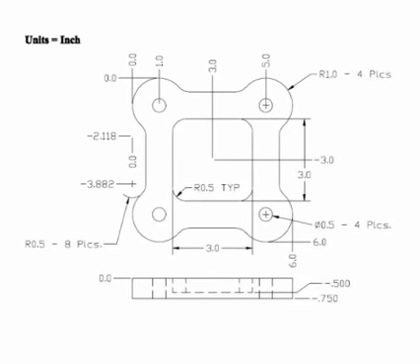We are now ready to begin our programming and machine the first operation. From our demo part print, you will see that we have a surface area of 6 inches positive and 6 inches negative to be machined. Our tool for this operation is a 1 inch diameter or 0.5 inch radius end mill.